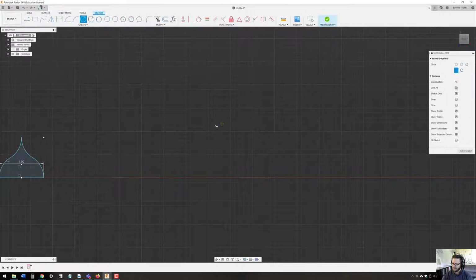So this is going to have a little bit of setup. I'm going to start with a circle. A Tudor arch is going to be a combination of a couple of circles and a couple of arcs, but we need to have the arcs match and be tangent. So an easy way to do this, we can create a quick circle. Make sure that I'm paying attention to the radius. Okay, so this one is 1. I'm going to put one right next to it that's also 1.